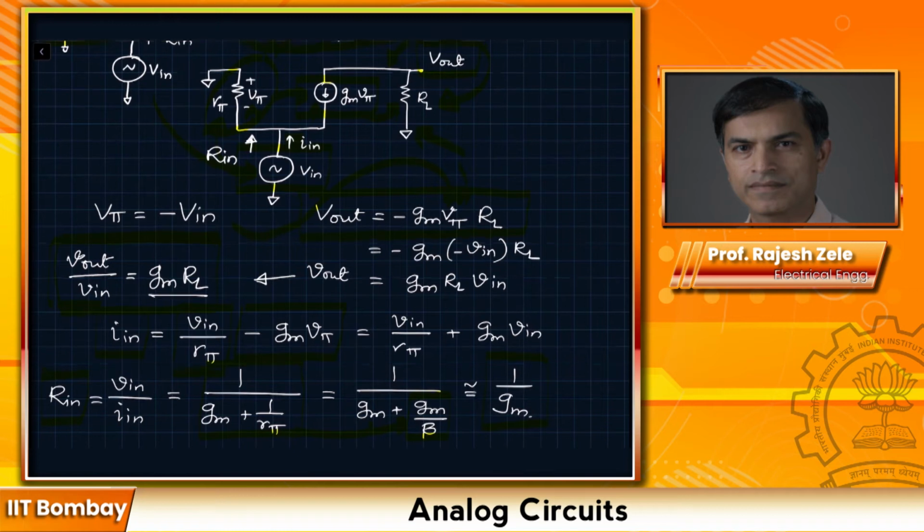So using Gm, what we can do is we can accurately control the input resistance by controlling the current flowing into the transistor. So this is very useful when it comes to high frequency circuit design. And there you need a fixed value of the input resistance. You may have heard 50 ohm termination or 75 ohm termination depending upon if you're dealing with cable or wireless antennas. That's what this resistance we are talking about.